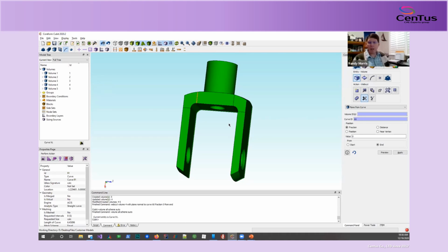If these were just contact surfaces and there was slippage that I wanted to analyze, then I wouldn't merge, right? So I'd want those two surfaces to stay separate, and because I put boundary conditions on them, analyze them for contact. In this particular case, we're analyzing effectively this one overall knuckle, this one volume, by merging these 5 volumes together. In the end, you'll see we still have 5 volumes, right? We still have volumes 1 through 5, but they will be imprinted and merged so that we can put a continuous mesh on the knuckle.